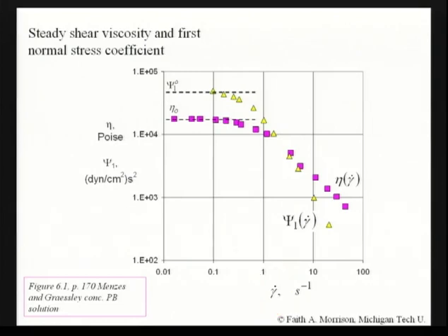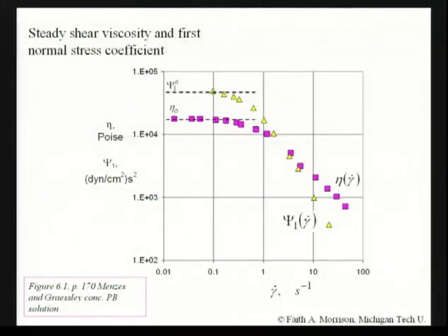It's always positive. Even though when you shear, actually, this flow has, let's say, in my chosen coordinate system, a positive shear rate. But if I turned it the other way, there would be a negative shear rate. But there's no real fundamental difference between these two flows. I just went left or I went right. And the magnitude of the rate of deformation in both cases can be the same if I move the plate with the same velocity. And so that's why these will always be reported in terms of gamma dot, the magnitude of the rate of deformation tensor.